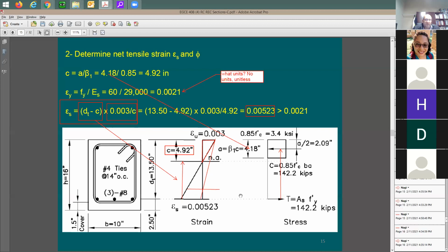When you put lots of reinforcing, they're going to be sharing the same force, correct? Just imagine that you have a beam here and then you start to load it. You're going to have tension and compression in the beam. You understand that, correct? Yes. This tension force, if you put a couple of rebars, these 2 rebars are going to be taking this tension force, right? But if you put 10 rebars, each bar is going to be taking 1/10 of this force compared to 50% of this force.